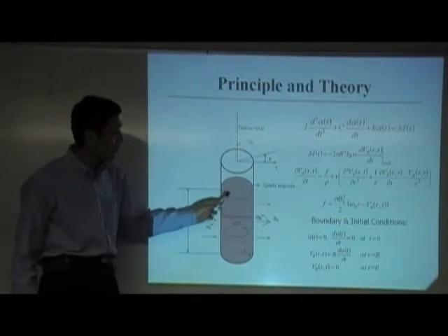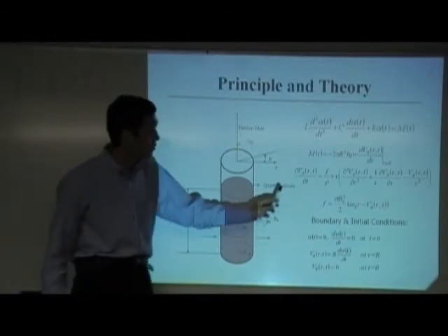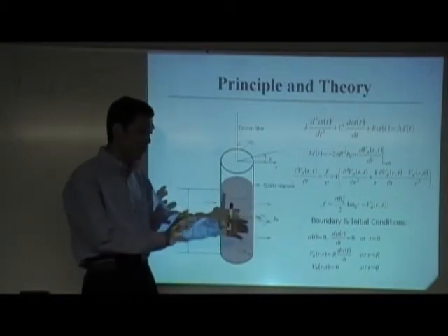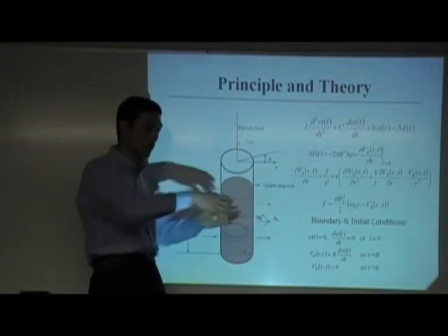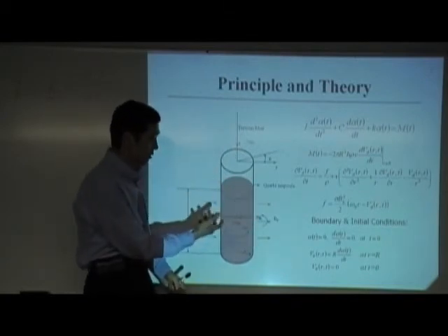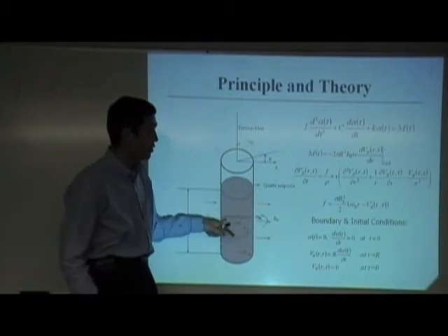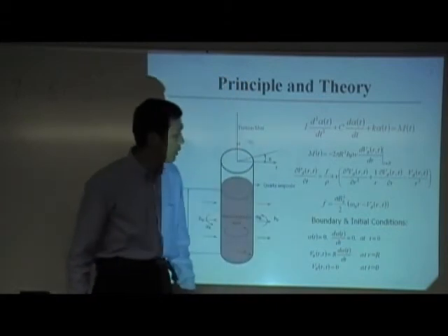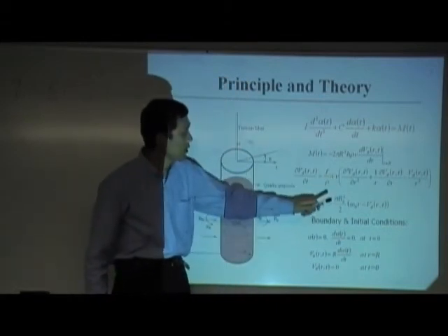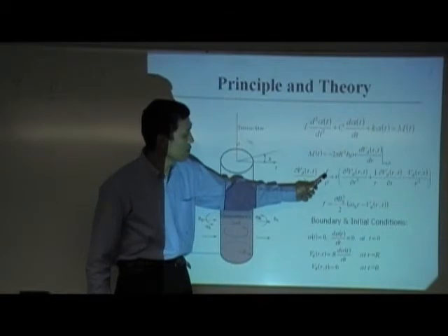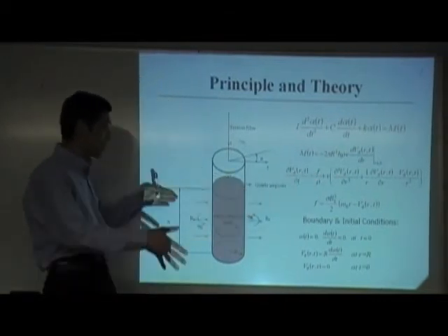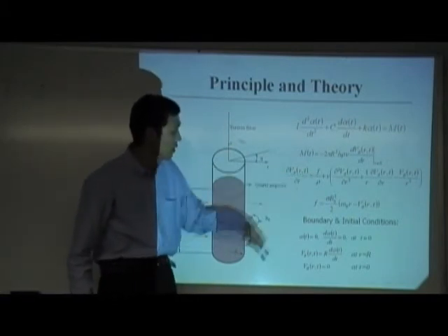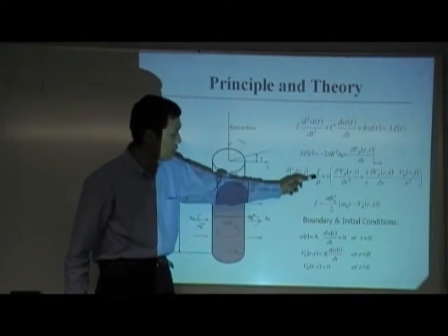On the liquid side, you have the Navier-Stokes flow equation. This is a transient term, because the liquid is flowing first this way and then that way, based on the position of the vessel itself. And you have basically the R direction only, with the viscosity here. And then you have this magnetic force. Outside you have a rotating magnetic field acting on this, so that's why the magnetic force is over there. This is the body force of the magnetic force.